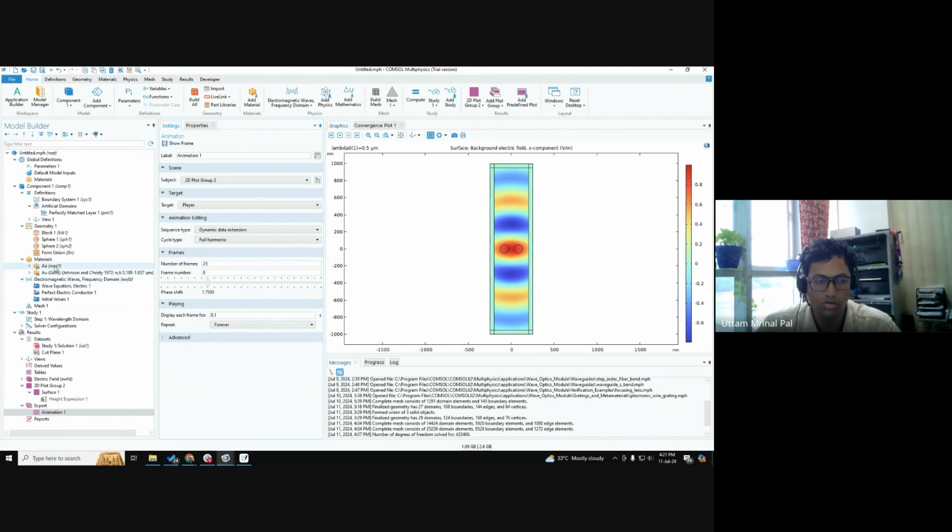So you can change it to the water domain and then launch the wave. That should not be a problem. But it is assuming that this domain is constant at this particular place. What you can do is a parametric sweep of this motion, with the particles moving away and close, and then you can see what is the enhancement based on that motion. But doing this time dependent is very difficult.